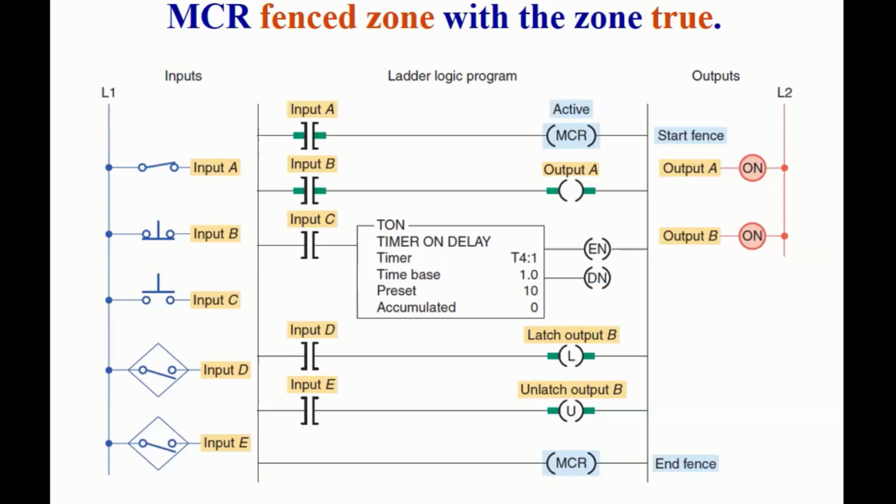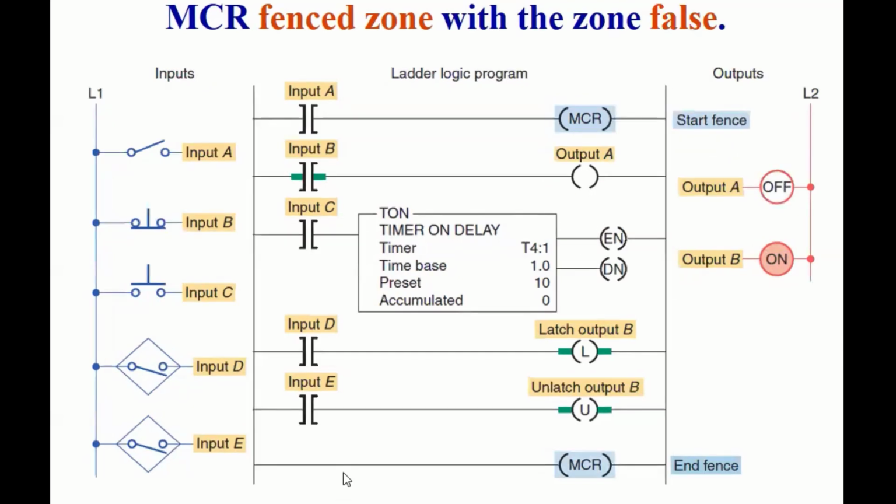and the latch instruction has its pair or partner, which is the unlatch. And so they both have the same address or label, if you will. And what you need is a trigger to latch and a trigger to unlatch. And you're eliminating other accessories that you normally use to latch a circuit with the latch and unlatch instruction.